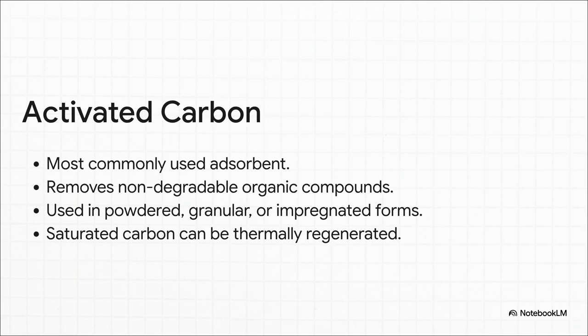For your exam, you need to know this stuff is fantastic at removing dissolved organic compounds. It comes in different forms too. Powdered activated carbon, PAC, you can dose that directly into the water. Granular activated carbon, GAC, that gets used in filter beds. But here's the key operational detail. Once the carbon is totally saturated with contaminants, you can recharge it, thermally regenerate it in a super hot oven, and use it all over again. That's absolutely vital for keeping costs down.